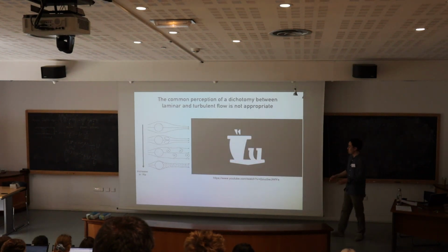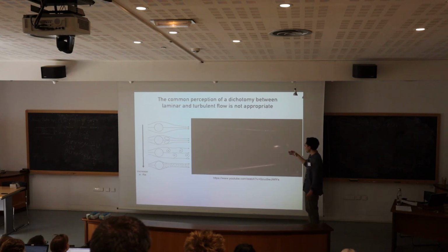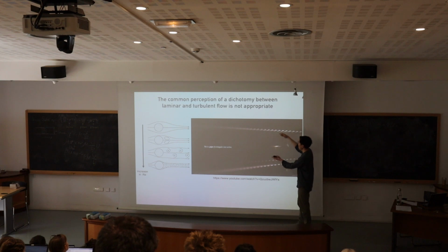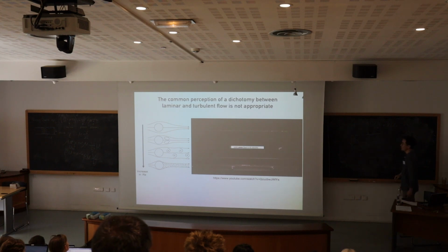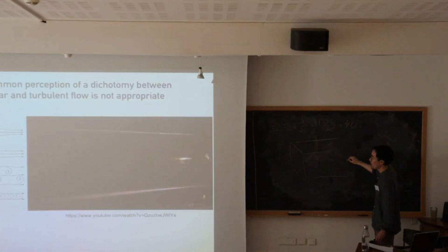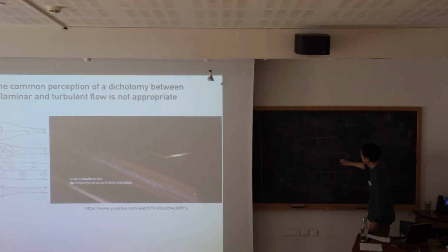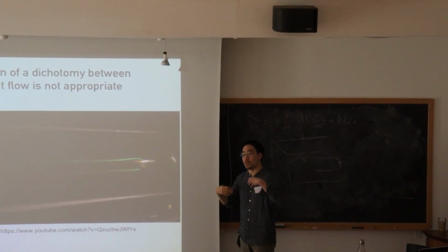So to give you a more visual understanding, I will share one YouTube video. Very simple, but I think it's beautiful. You have a flume, fully saturated, with transparent glass, rectangular. And you have one grain. There is background flow. And this one has a nozzle at the back, so it can slowly release dye into the background flow. Then, systematically, step by step, we will increase the flow rate.